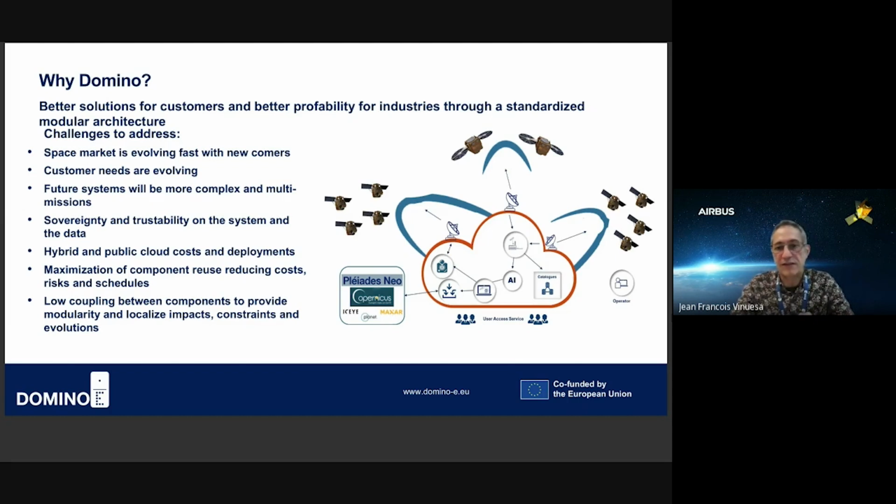So what we have seen is that these things mean that you have a modular architecture. You have the ground segment, which is basically 3 or 4 blocks. You have the image ground segment that is going to take the data from the antenna and make it into a product. You have the mission ground segment that deals with all the scientific or technical characteristics of the system. And you have the control ground segment, the control subsystem, that is going to check the safety of your platform, do the maneuvers and all this kind of thing.